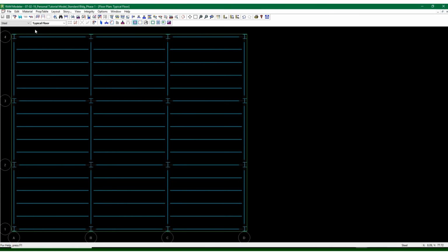And like I said, I will be changing the property that I assigned to the deck, the elastic modulus, because for a semi-rigid diaphragm, those properties ought to be calculated. And I'll get back into it. We'll talk about semi-rigid another time.